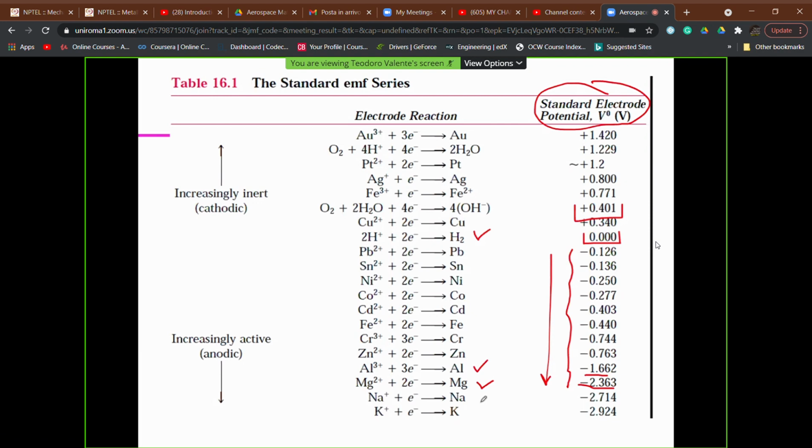But we also said that we do have, for example, in the case of use of this kind of alloys in aerospace, military specifications which tell us that we need to put some protective coatings on the magnesium alloys, otherwise we will experience corrosion phenomena which cannot be tolerated for the components itself.